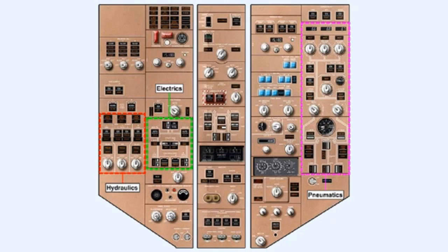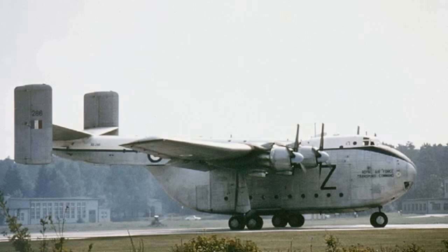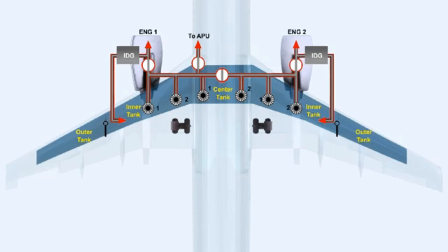The auxiliary power unit can provide the necessary power for operation of an aircraft's electrical, hydraulic, and pneumatic systems. While earlier aircraft used the piston engine to drive their auxiliary power units, it soon became obvious that the gas turbine engine was safer, lighter, quieter, and more reliable. The gas turbine engine auxiliary power unit uses AVTUR, which is the same fuel as the main engines use, so the problem of fuel storage and fuel management systems is minimized.